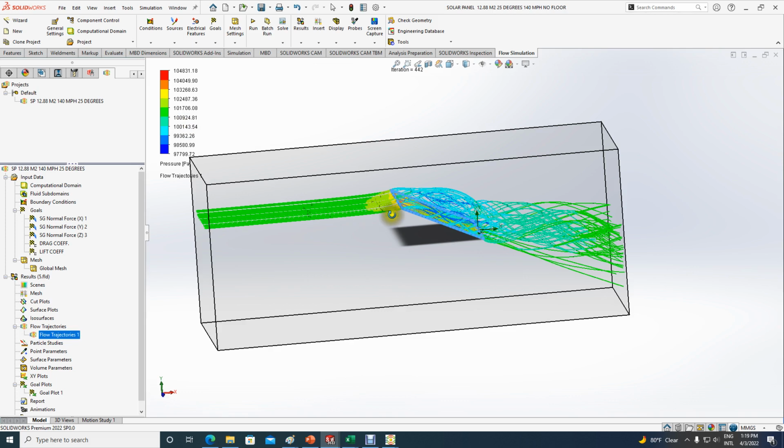Let's say I'm using three times the core size basically for this length here, so I can definitely reduce to at least, I don't know, easily 2 without any problem. I can see no disturbance on this zone. Make that mesh smaller. Let's see.